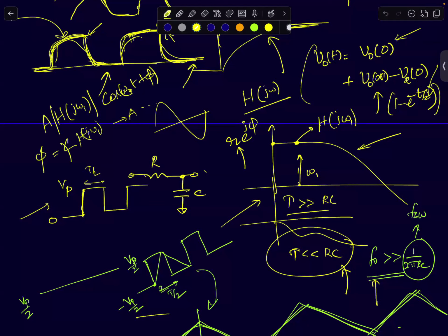So that's why frequency response is a very powerful tool. By looking at it, you can predict how the system will behave if I feed different sinusoids of different frequencies. A DC signal is a sinusoid of 0 frequency, which means it's going to be constant all the time.